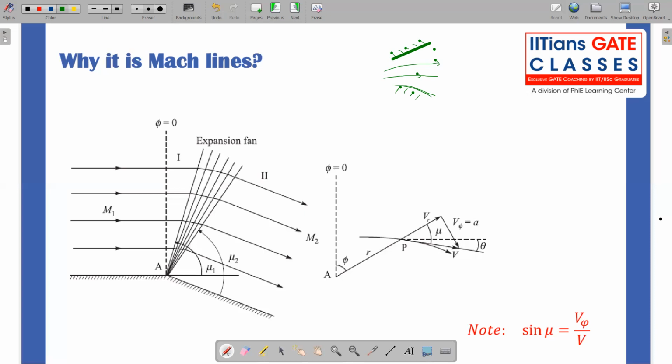That's what we will discuss once we come back to nozzle flow. But here, this idea can slightly be taken. Whenever the flow sees a diverging section like this, it accelerates. So what happens whenever the flow has to accelerate? One would expect the static pressure to decrease, right? If the static pressure is decreasing, that means velocity is increasing. So the pressure energy will be transformed into kinetic energy, right?